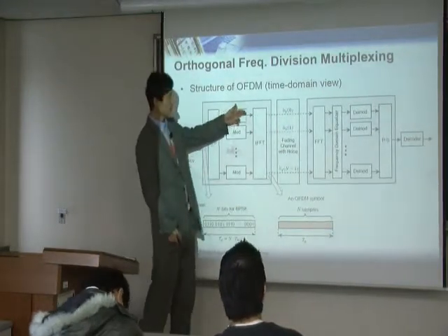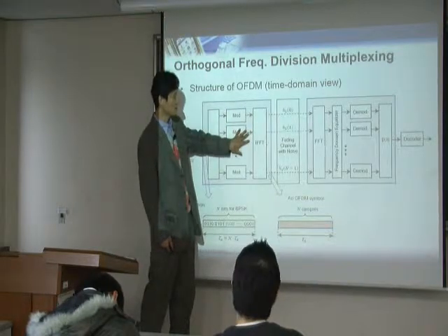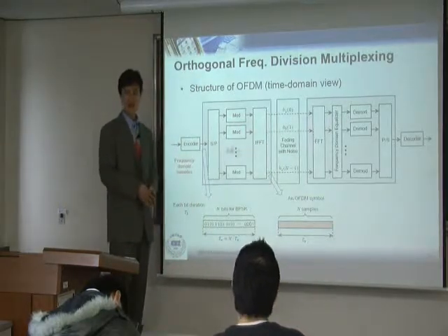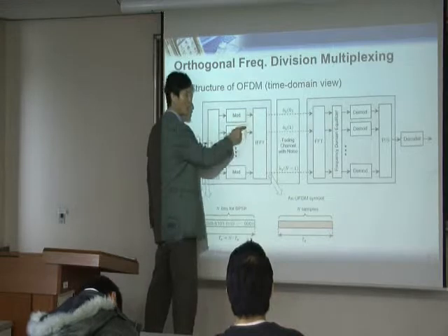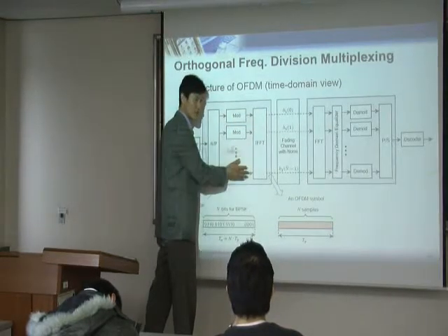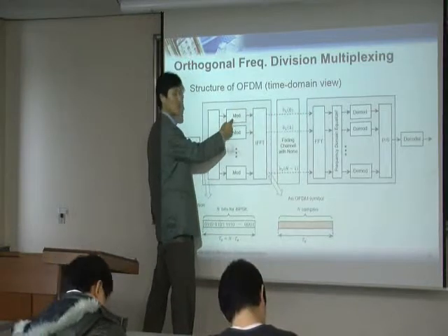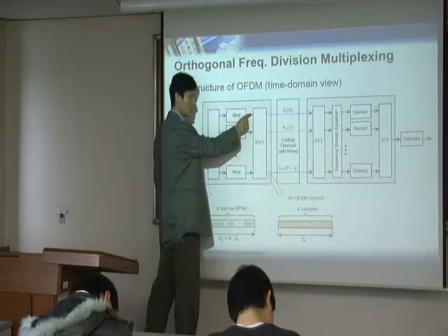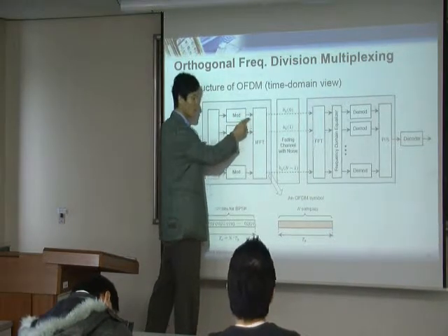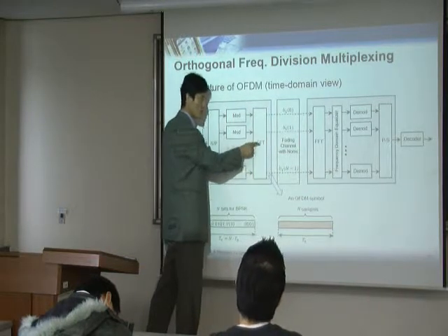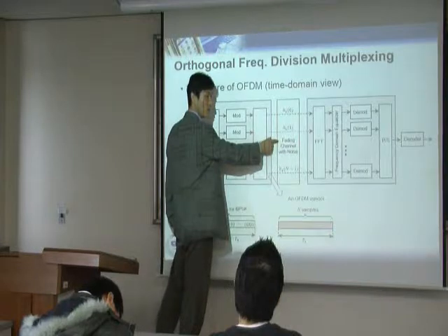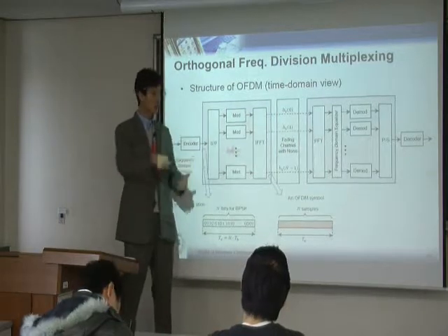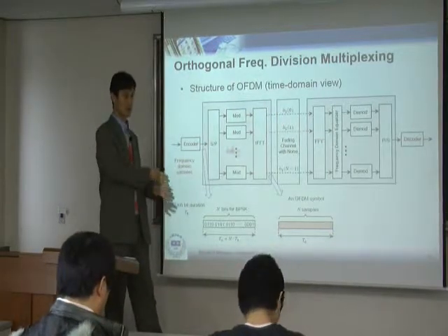Okay? Let's say you have some frequency domain samples, going through the IFFT, then you have time domain samples. Now in the worst case, maybe an extreme case, let's say you have all the same value, like 1, 1, 1, everything is 1. That's your original data. This is BPSK, and our information is all 1, so when you modulate it, you still get all 1. Suppose that's the case. You have all 1 going to the IFFT, the time domain sample, what do you have? In frequency domain, you have all 1, so flat. In time domain, you probably have an impulse, right? Impulse like this.